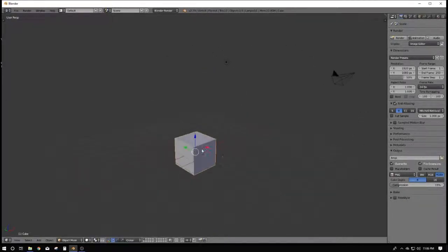What's really nice about Blender is that it has a bunch of shortcuts. So say I want to move this lamp around. All I have to do is select it, and I can hit G, and that will allow me to move it wherever I want. But it's kind of awkward to be moving it in this view, and you can't really pan.